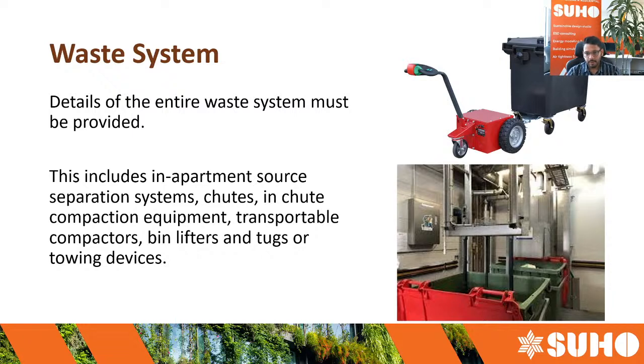And one more thing here, supposedly we don't have enough space for 2 chutes where we can put garbage or the recycling waste. We can go with the diverter chute, where one chute is there, and when it goes to the waste area, it diverts into 2 separate streams, and while putting the waste, residents have to click the button for which stream they want to put their waste in. Either it's garbage or it's recycling. So architects also need to mention that in the drawings. Once we propose it and it's approved, then architects can mention it in the drawings to make it clear for the council.